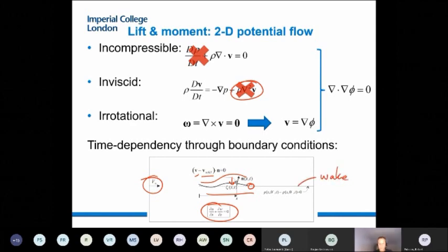It is possibly the most complicated bit to analyze in anything that has to do with aerodynamics. In the simplest model, which is what we're dealing with here, the wake is defined simply as a zero jump of pressures, by assumptions of linearity, on a line. I'm assuming this myself now, a line that goes along the chord from the leading edge of the airfoil to infinity, but never moves from the horizontal plane. In reality, these may oscillate and be quite complex. This is a first order approximation to the problem.